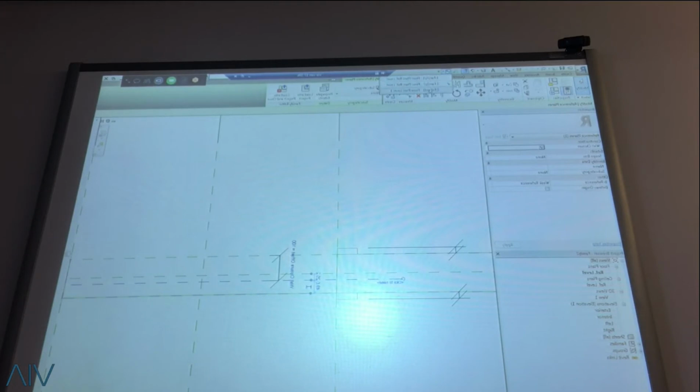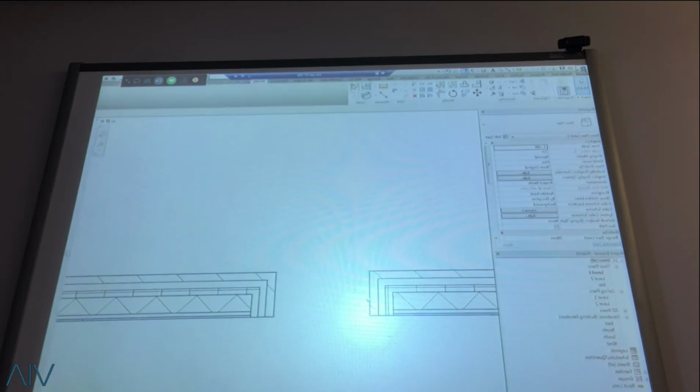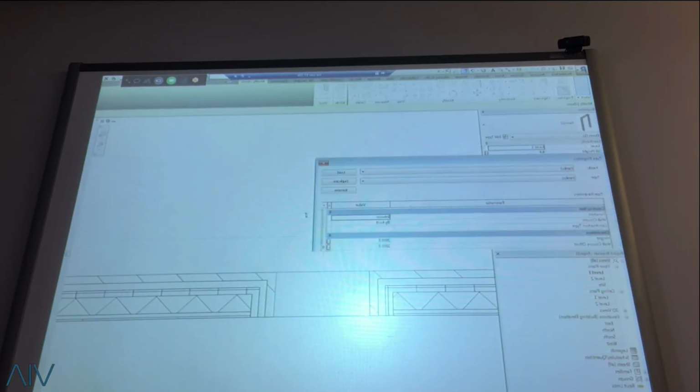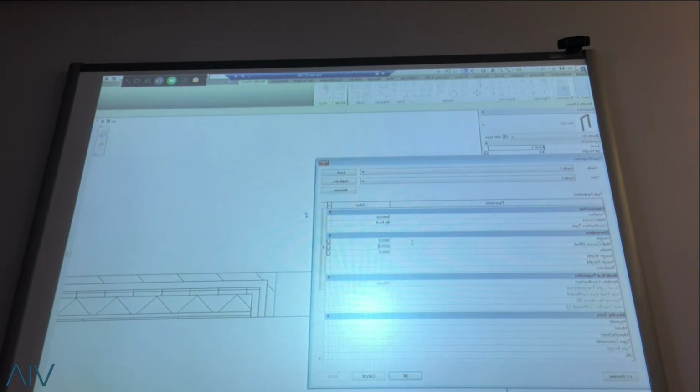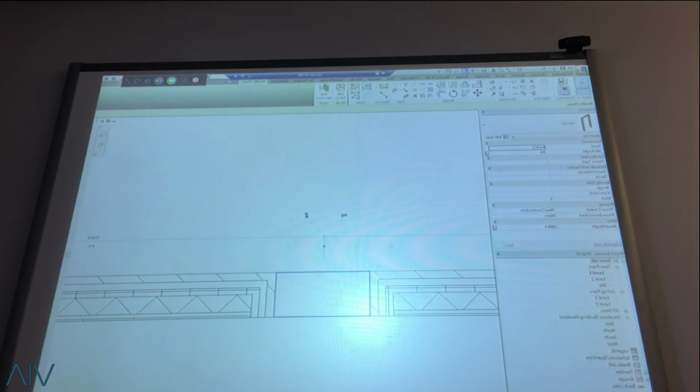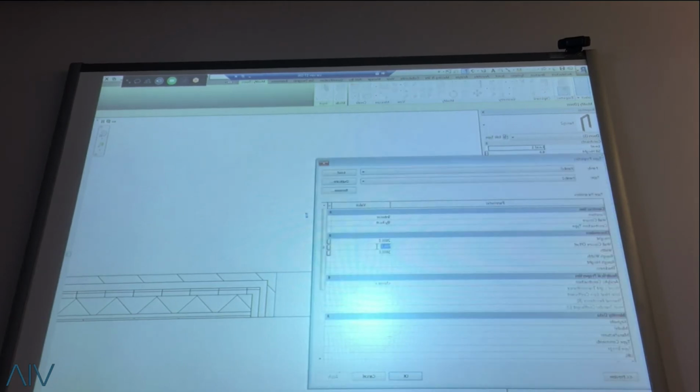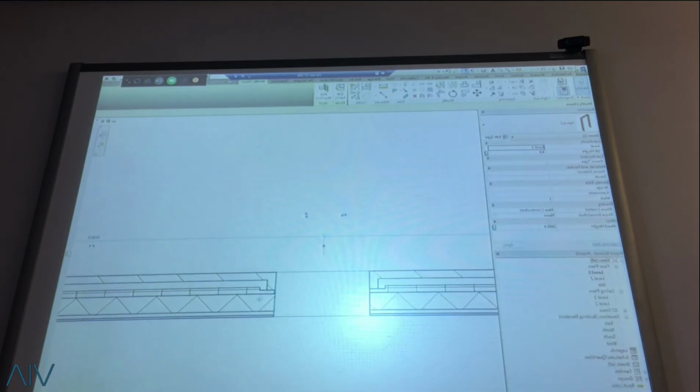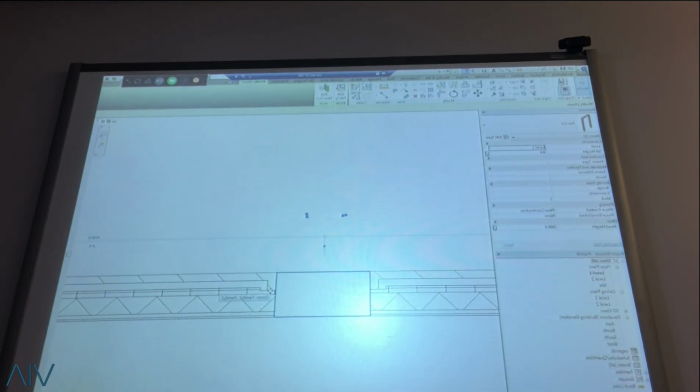Then when I go into the project, let's say I wanted to find this door and have the wall closure offset, let's say 500. Oops, too much. Let's say 200. There you go. So basically, it controls the wrap. You can do that inside the door or window family. It's one of those hidden features that nobody knows.